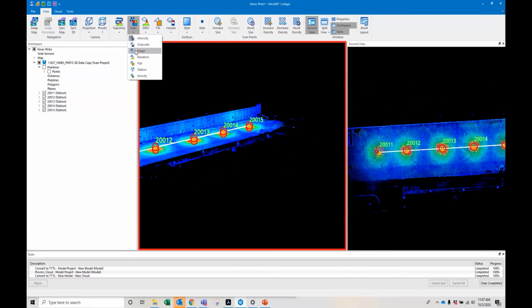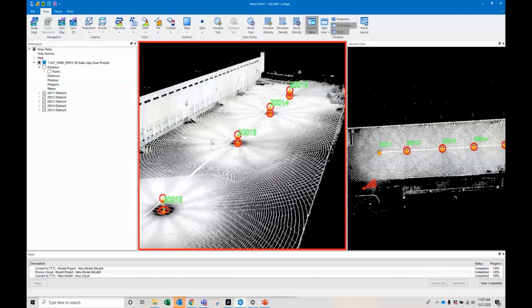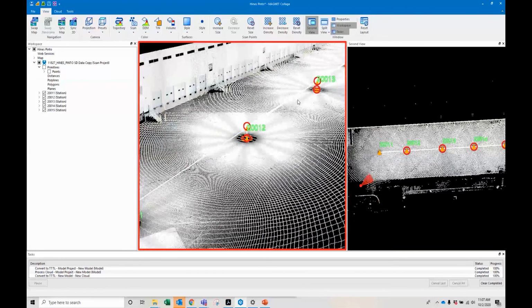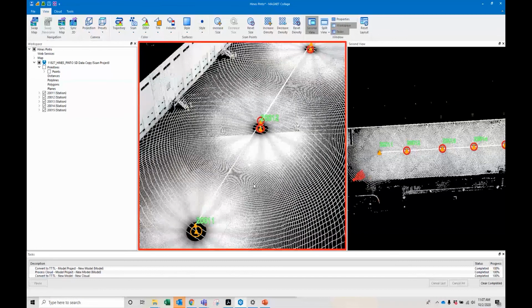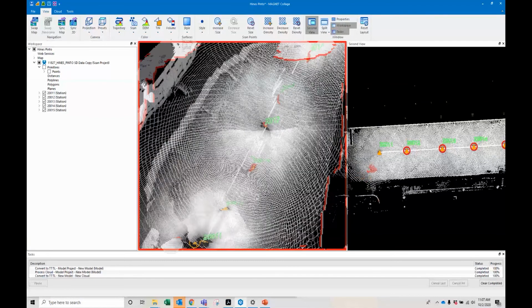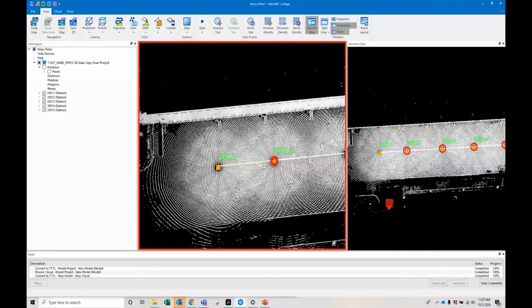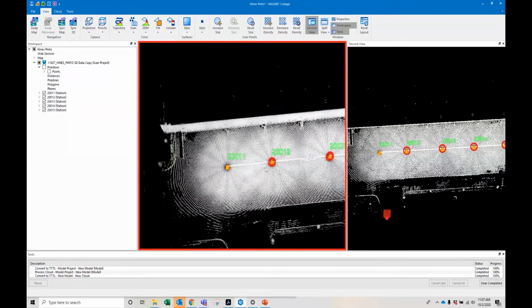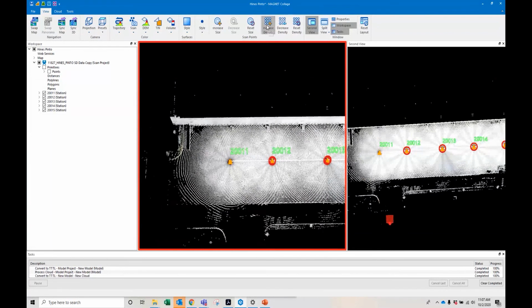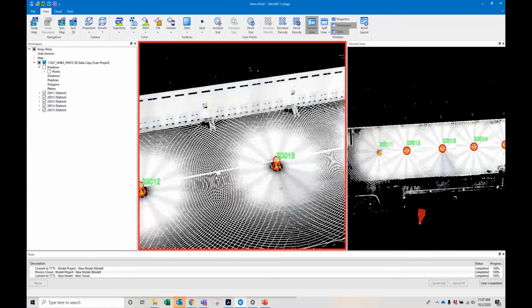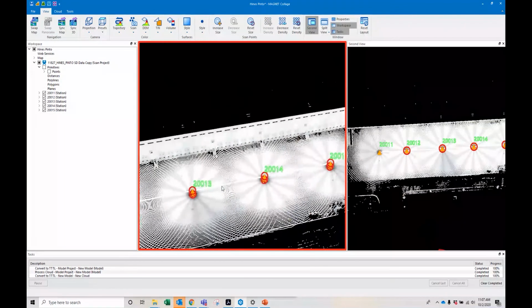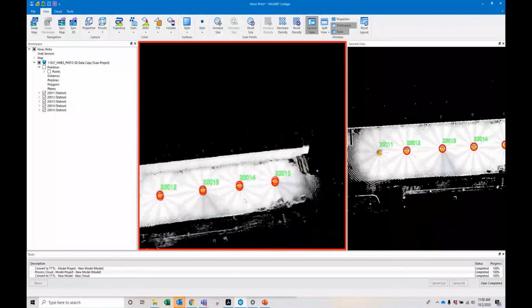Let's turn on images. Bunch of loading docks. So what we see here is this scanning technician. He went in and he set up 5 times. And he tried to get somewhere by the inlet, but also somewhere where he can capture the most amount of data per setup. So as you see here, let's increase our density so that you can see as many points as possible. He's got good overlap of his scans, and he goes all the way down.